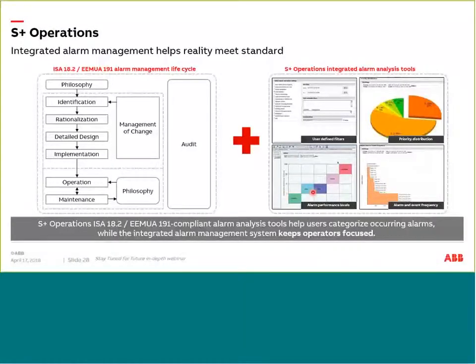It looks at your entire system for the time window that you've defined and puts an X. Where we want the X is typically in the blue area. Blue is where it's stable and robust. Green is more where it's predictive. So now you're not inundating the operator. You have less than 10 alarms coming in every hour or something like that. If you're up here, you have 1,000 alarms coming in every 10 minutes, and you're inundating the operator, therefore rendering the operator not as effective as he or she can be.